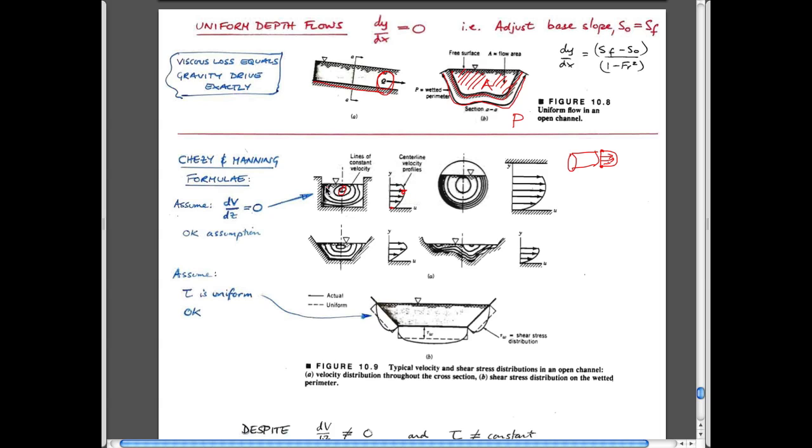And as you get progressively to the sides, around these areas here, you'd expect it to be relatively small. So if you like, this is slow, and this is fast. The slow might be zero. It probably isn't zero, because what happens here is you get this boundary slip, this kind of boundary layer effect, where there's some finite velocity occurring at this thin area just due to boundary layer effects.